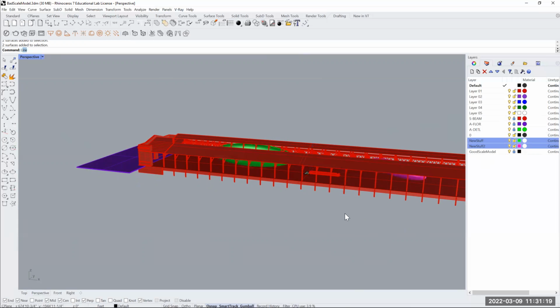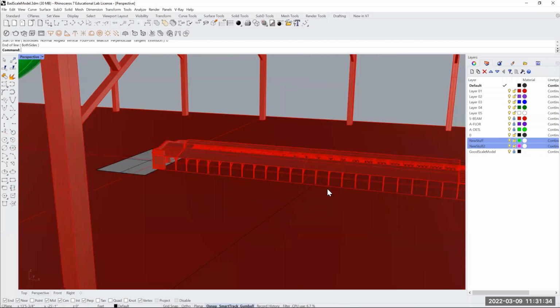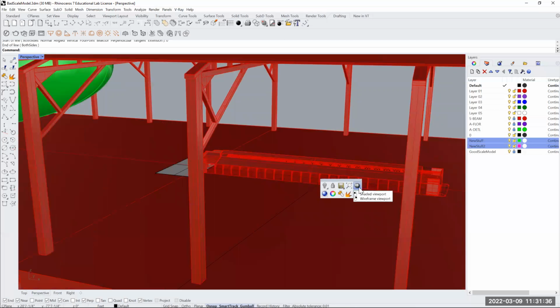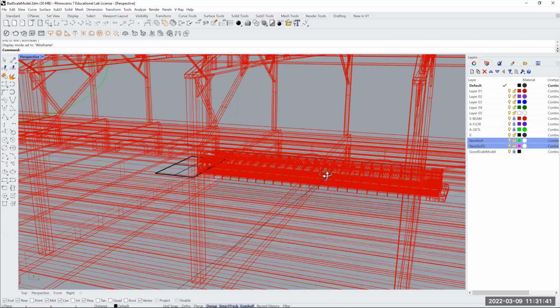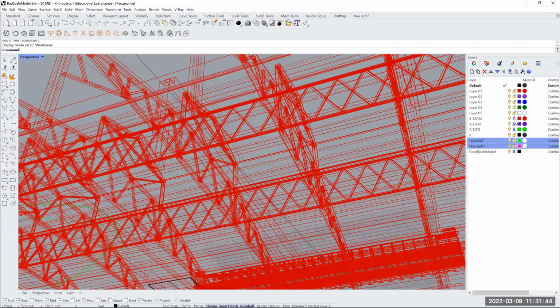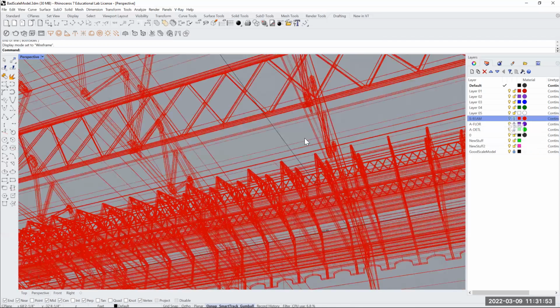I'm going to deselect that and I'm going to do line. That's a command, as you know, line, and I'm going to press the number 0 and enter, and that will create any line. Doesn't matter where it goes. What matters is that it actually goes from the 0,0. That's the 0,0 of our project. You know that if I go to wireframe, that's actually starting in the meeting point of the red line and the green line. So that's good. We have a line in the 0,0.